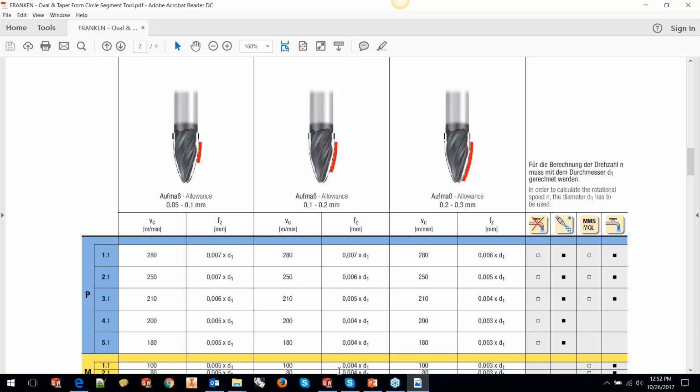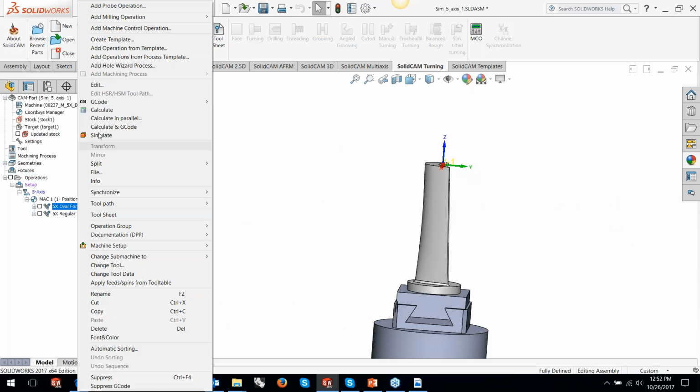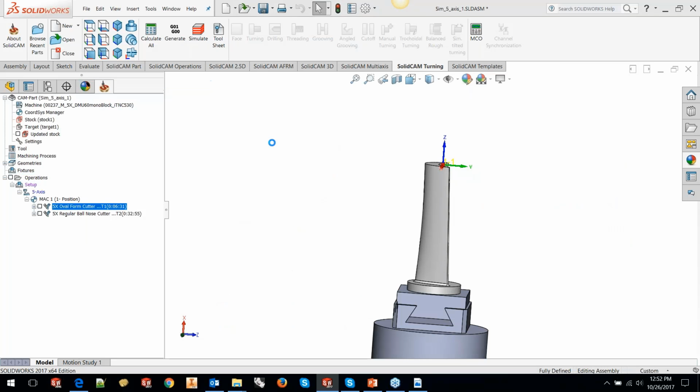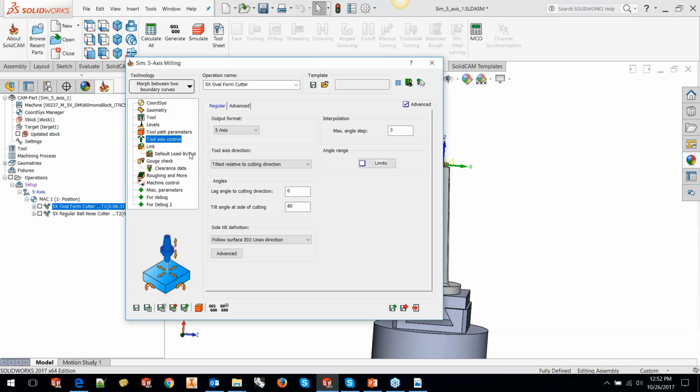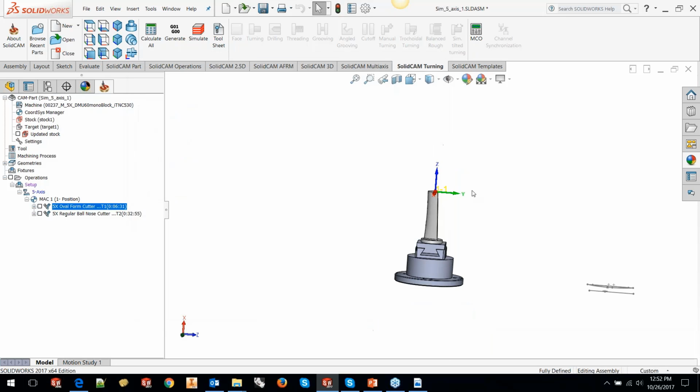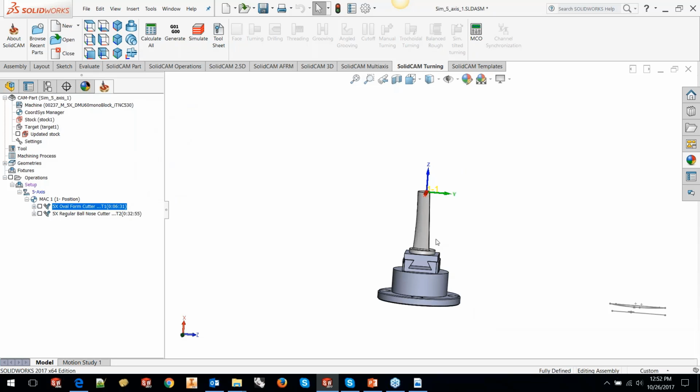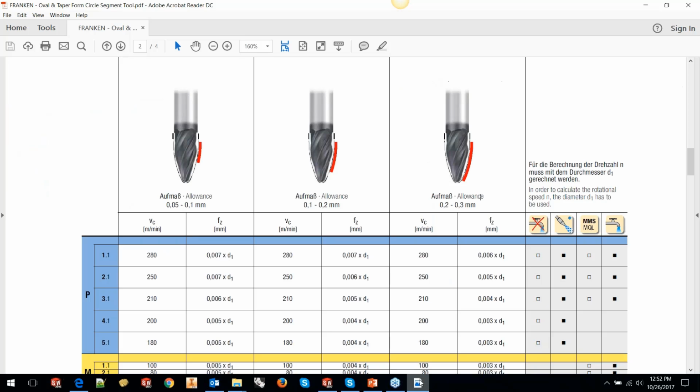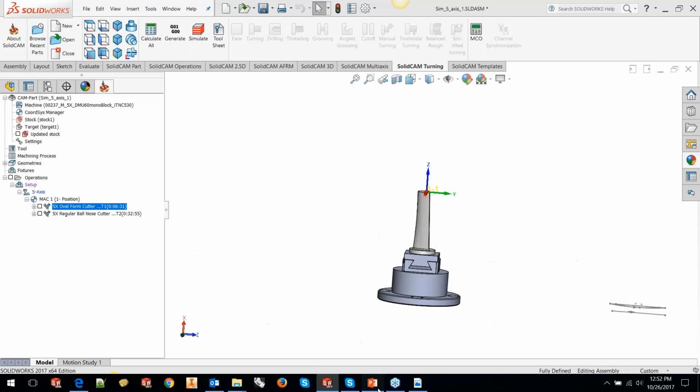And the most important, the tilt. What I've done here is I have used a tilt of 80 degrees, so about 10 degrees away from the surface, to get the flank to cut the entire surface. Very important addition to our portfolio in 2017, the circle end mills. Okay.